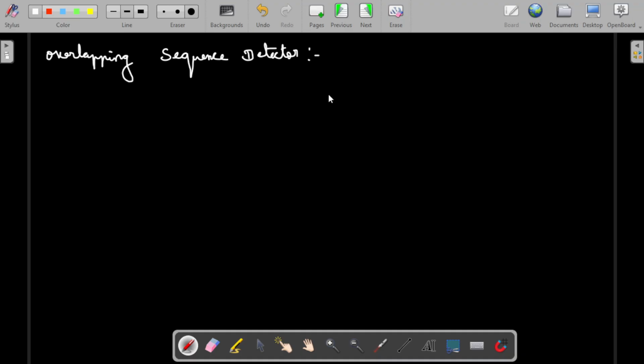Okay, so similarly to how we previously started, the same thing. Present state (PS), input, next state and output. The initial present state will be S0. When the input is 0, it will go to S0, the same S0. When the input is 1, it will go to the next state. Output will be 0 in both cases.